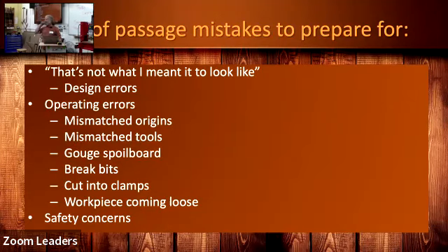In my system, when I do the design, I have to say tool number 6 is my V-bit tool. And that number 6 bit better match what bit number 6 is in my machine control software, or I'm going to be cutting with the wrong bit. Been there, done that. You assign the numbers to whatever bit you. Correct. I assign the numbers in my machine software, and then I have to select that proper number in my design software. I have the gouge in my spoil board to show you where I did not do that.